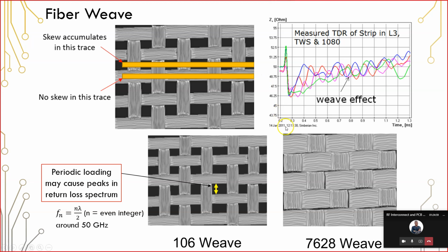The result of this, when you measure it on a TDR, a time domain reflectometry measurement, is that there is some variation in the impedance that can be measured, or in this case simulated. In this particular example, this was simulated with Simbeor, and the result is this very wavy behavior, in that it appears there's a lot of impedance variation along this trace.